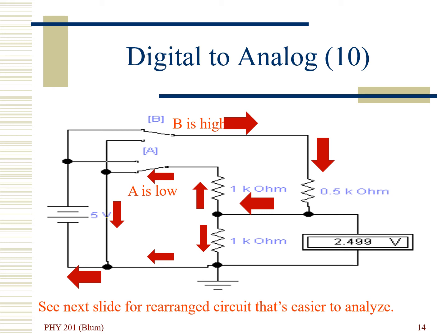So I'm going to show you on the next slide. They have a wire connection coming between them, and that's one wire connection. And then there's a wire connection on the other side that loops through the switch down and next to the ground. So those 2 1 kilo ohm resistors may be tricking you and trying to tell you that they're in series, but with the way that we are connected right now, they are in parallel. And now let's look at them in parallel and finish the analysis.